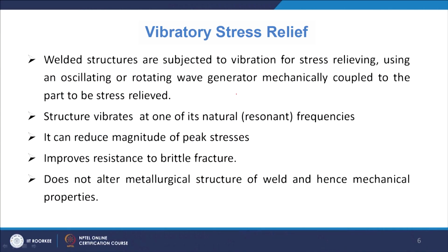Then the next method is the vibratory stress relief. In this case the welded structures are subjected to vibration for stress relieving, using an oscillating or rotating wave generator mechanically coupled to the part to be stress relieved. So basically we use the vibration to relieve the material of the stresses.